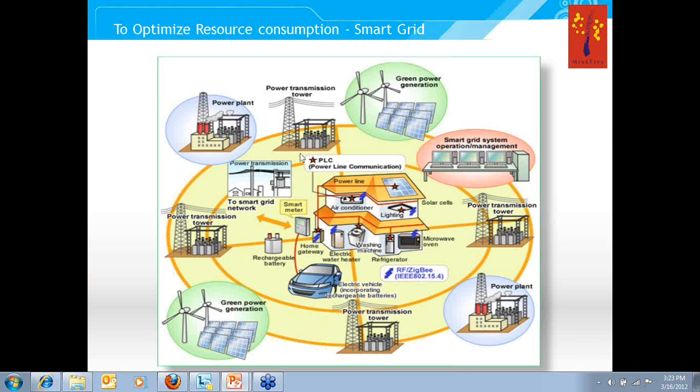One example of this is a sensing system that can detect transformer issues and take actions. Systems are available where a lot of sensors are attached to the transformer, and things like oil temperature and water content in the oil are measured continuously, and the predictive analytics algorithm inside the system can predict an impending problem and take action.